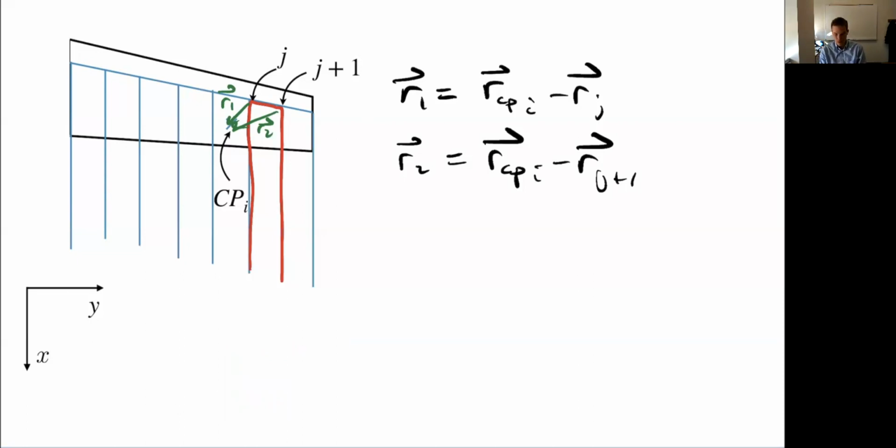I should also note, again, that you should look in the book for details if you're interested, but that in almost every case, the wing is symmetric. Unless we're doing a case with, say, side slip, some sort of maneuver, then we want to actually retain that asymmetry. But in many cases, this is symmetric. I always still need to include the effect of the left half, but I don't have to solve for all the circulations on both sides, because whatever I solve here is going to be the same, just mirrored over on that side.